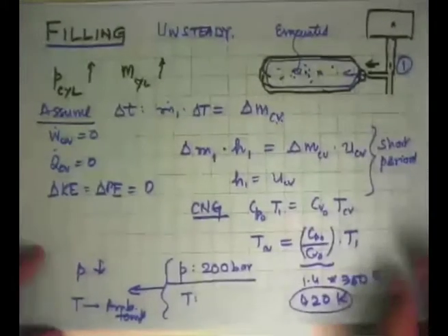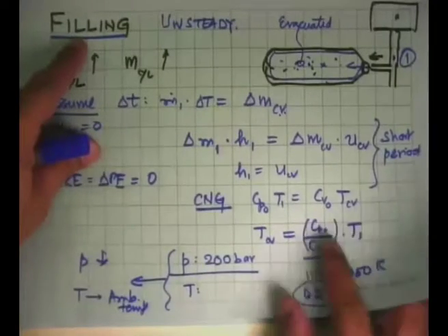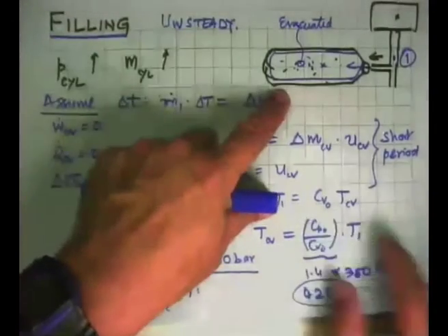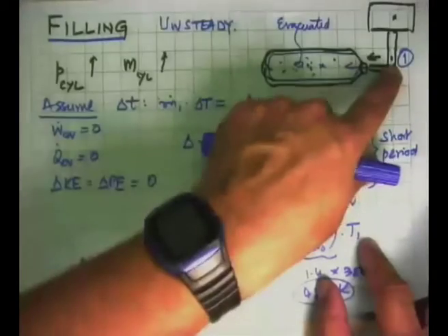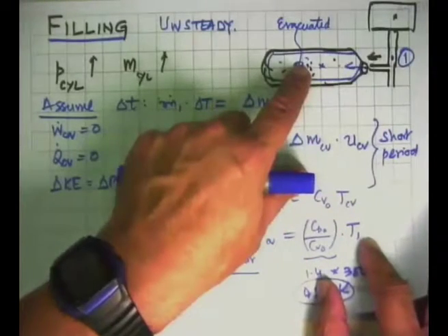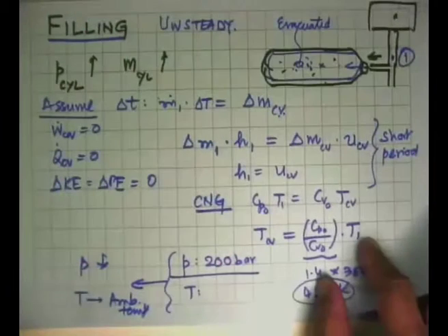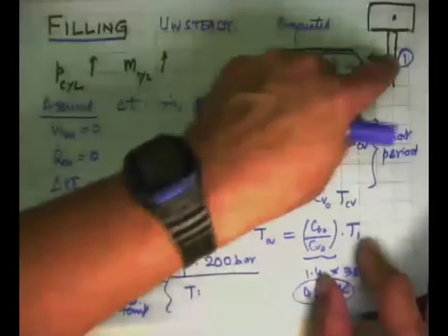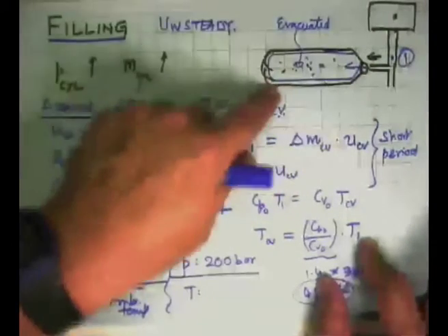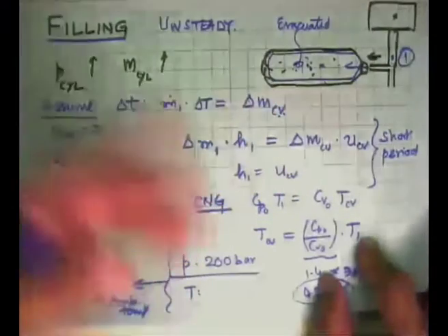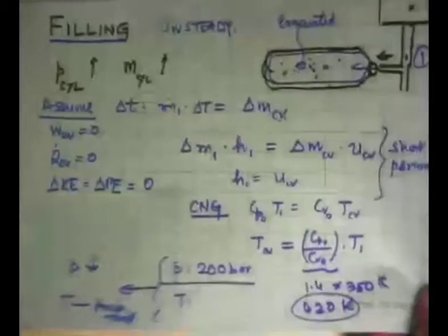But it's important to know that this is what filling does, and there are many other cases where such things happen. We can look at the case where this was saturated liquid and it was evaporated, and ask what will happen. That's the example when your LPG cylinder goes for filling. It is initially evacuated and then you are pumping liquefied butane into it. And we can say that, well, I am putting in some liquefied butane. Am I actually getting liquid butane inside the cylinder at all times? I'll leave that question to you to think of.